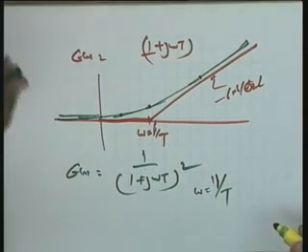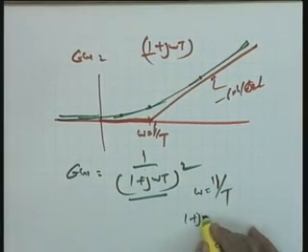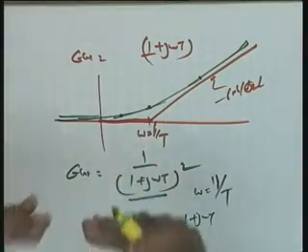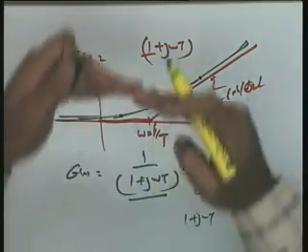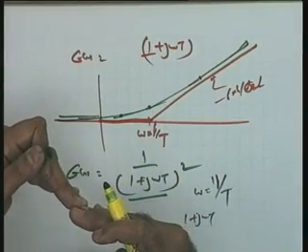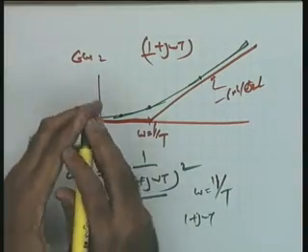Note the word corner frequency: it is omega equal to 1 over t when your factor is in the pole in time constant form. 1 plus j omega t is the form of the factor we have taken. Now, minus 40 dB per decade, and how about the errors? Please see that the errors will get algebraically added up: minus 6 dB at the corner frequency, minus 2 dB at 1 octave below and above the corner frequency.